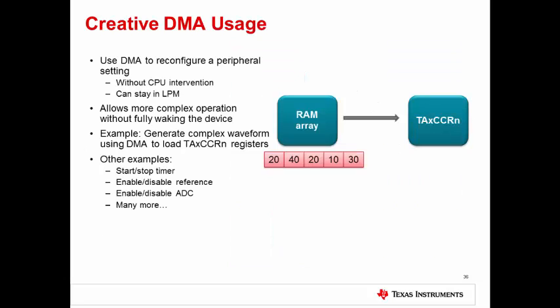DMA can be used in many other ways, which can get quite complex but also very creative. One example is using the DMA to generate complex waveforms, such as a timer-based DAC. By loading the timer duty cycle registers, the DMA can generate complex waveforms without any CPU intervention.